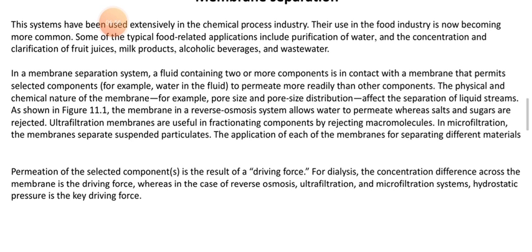So in this condition, the flow will always be from higher concentration to lower concentration. This concentration difference basically acts as a driving force in the dialysis process. But in the case of reverse osmosis, ultrafiltration and microfiltration systems, hydrostatic pressure is applied as the key driving force. It means we apply some kind of force to the liquid, and that is known as hydrostatic pressure.